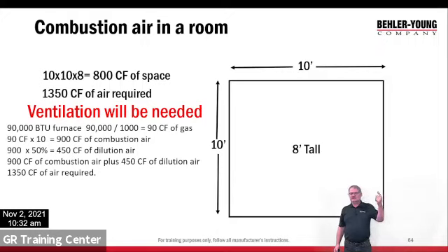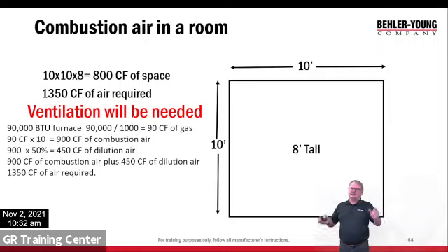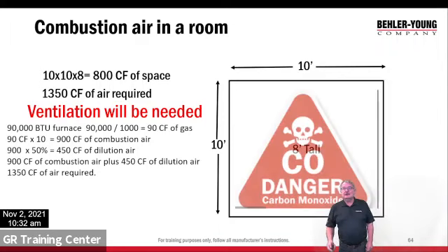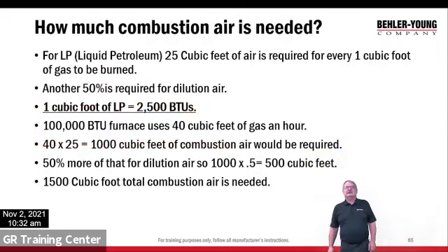You get that sealed room, the homeowner finishes the basement, makes a man cave down there, ties up that tiny little mechanical room. It's airtight, right? Because we don't want to hear that furnace and everything. And pretty soon, bad things happen. So carbon monoxide can be a problem. You walk in that room, you're going to smell it. Not the carbon monoxide, the aldehydes. But we can cause a problem here.